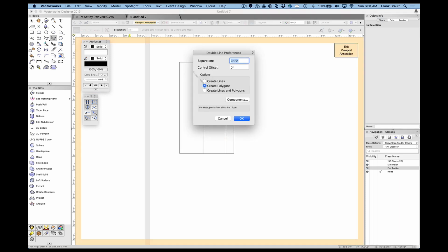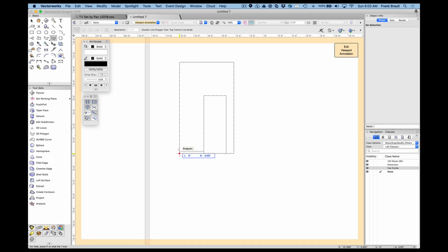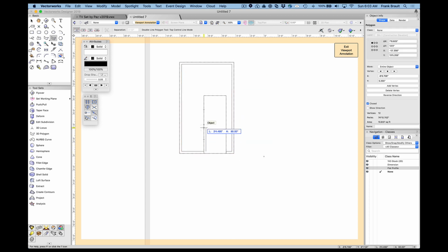Let's take a look at a typical workflow, where the tech director receives a series of elevations from the scenic designer. The process is simple and follows a traditional approach where the designer's front elevations are simply flipped and the framing is laid in. The TD creates a referenced viewport so that the scenic plates are not altered, yet any changes will be transmitted to the TD's construction set.